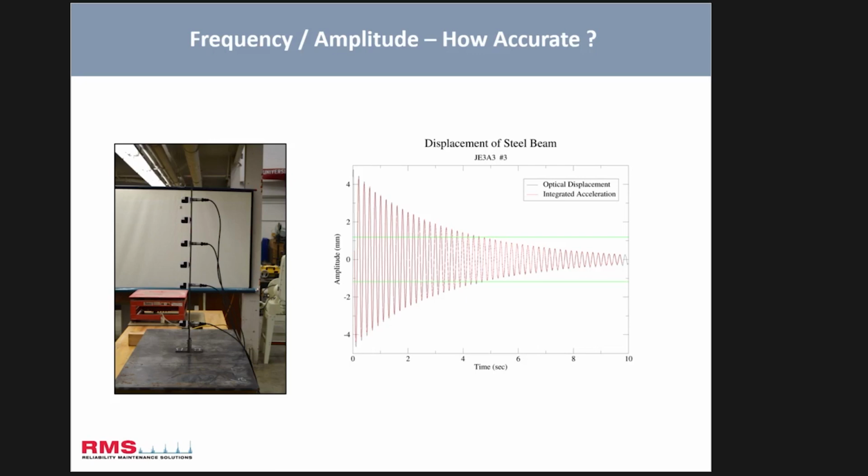So it's bad practice to ever measure something with an accelerometer and show something in displacement, because you've integrated it twice, which incurs so much error. We just don't do it. We can integrate once into velocity like we normally do, but never go again into displacement or on an overall level. We just don't do it. You stay in the unit that you're measuring. So for displacement, the camera is more accurate than an actual vibration measurement.